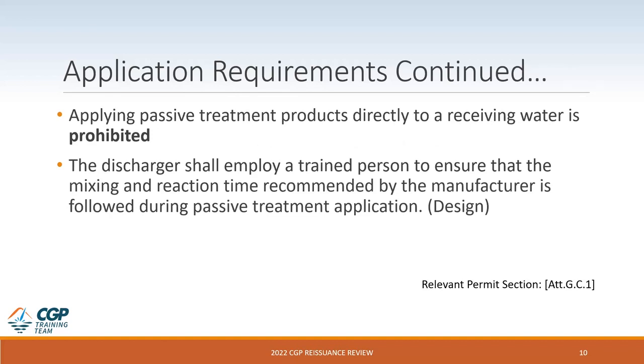Again, applying these products directly to a receiving water is prohibited, and the discharger shall employ a trained person just to ensure that the mixing and reaction time suggested by the manufacturer is followed during application. Now, this is listed in the application section of Attachment G in the 2022 CGP.